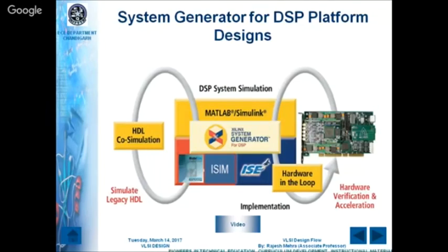The FPGA is programmed with your bit file after writing VHDL or Verilog code, and then again it is going to give you the output in 16 bits. The output is again in the form of zeros and ones. So if you want to view the actual waveform of your filter, again you have to use some kind of block that can convert this digital output into analog, right? Then we are going to use Gateway Out. Gateway Out will be responsible for converting this digital output, these 16 bits, into analog. So that analog output is going to show you the output of the filter similar to your MATLAB environment, right? If you have developed a low pass filter in MATLAB, you can easily view it from the waveform. That same waveform you will see after Gateway Out, that low pass filter.